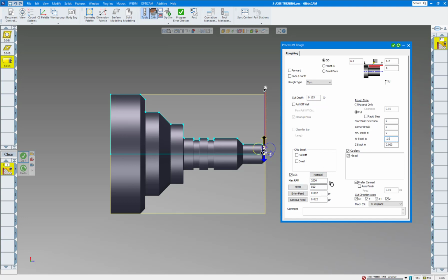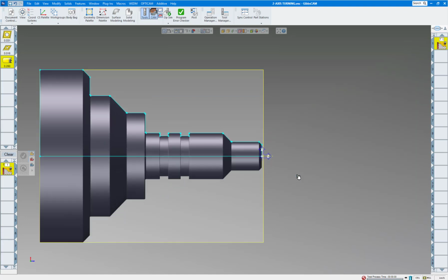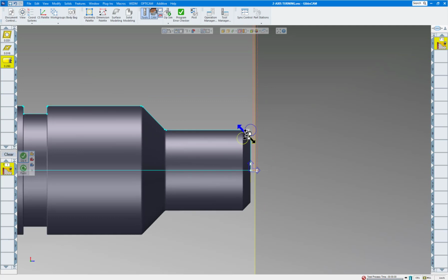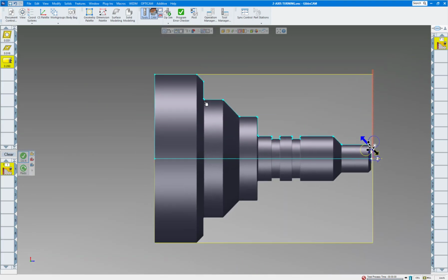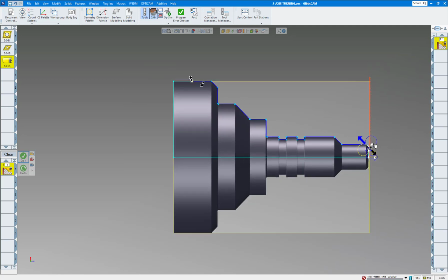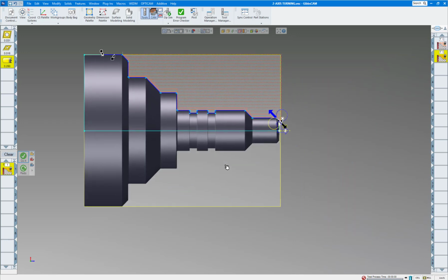Again, everything else here the same, and I'm going to show you something on here which we'll want to change. So I'm going to click on this little chamfer here. I'm going to drag it off my part a little bit. You can always right click and say move to a certain amount, or thou if you want. And then a trick to use to bring it back here is hold down the control key and the shift key and click on the line you want to finish. Since we're holding on the jaws here, I'm just going to pull it about halfway back there. If you wanted it exact, you could put a point here and have it snap to that point. So we're all good there. So click on do it, and it all looks good.